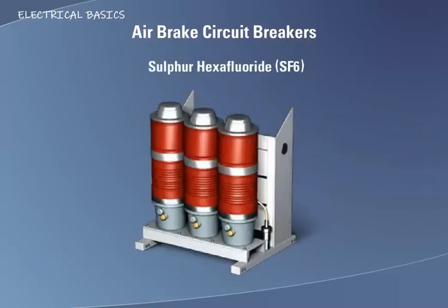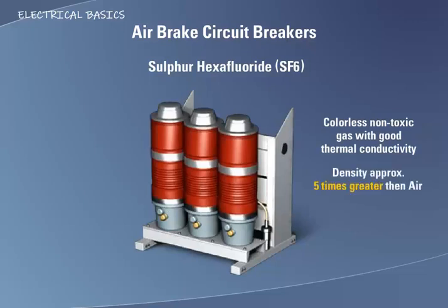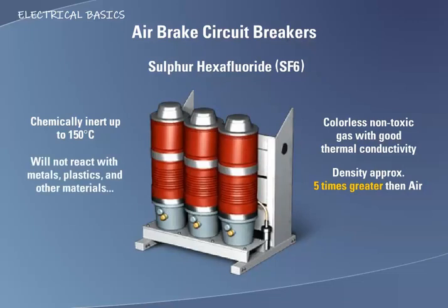Sulfur hexafluoride, or SF6 gas, is an alternative to air as an interrupting medium. SF6 is a colorless, non-toxic gas with good thermal conductivity and density approximately 5 times that of air. SF6 is chemically inert up to temperatures of 150 degrees Celsius and will not react with metals, plastics, and other materials commonly used in the construction of high-voltage circuit breakers. The principle of operation is similar to the air blast breakers, except that the SF6 gas is not discharged into